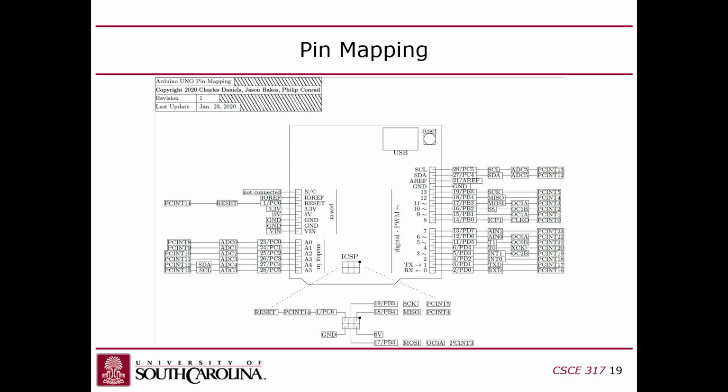And then also, as I mentioned last time, when you're doing GPIO, there are 3 GPIO ports, 2 of which are 8 bits and 1 is 7 bits. I don't know why they do it that way. So you get 23 bits in total spread across port B, C, and D. If you see PD6, that means bit 6 of port D. But you can also see that particular pin can be used for analog input 0, so that pin is also connected to the internal analog digital converter.